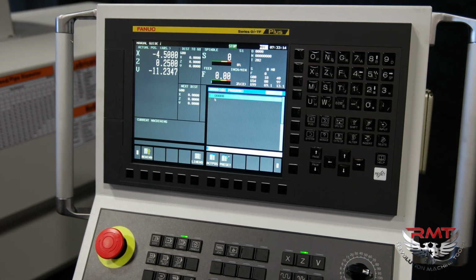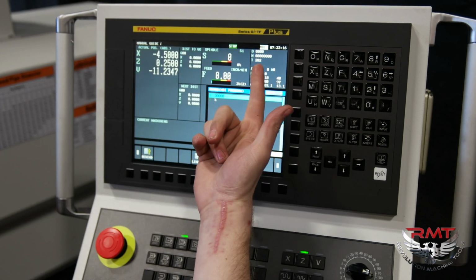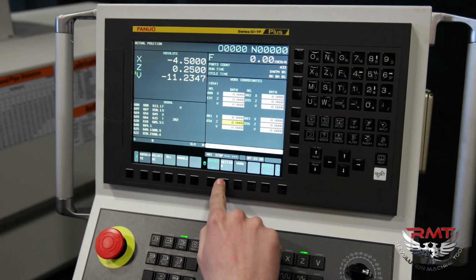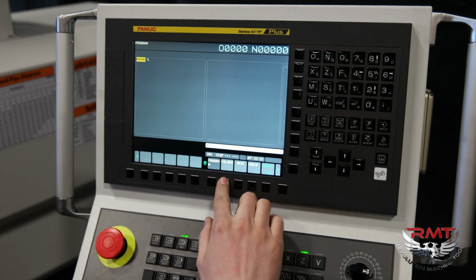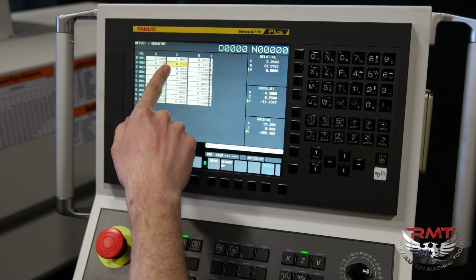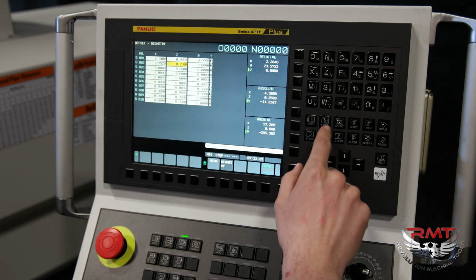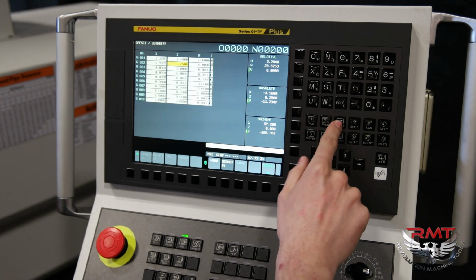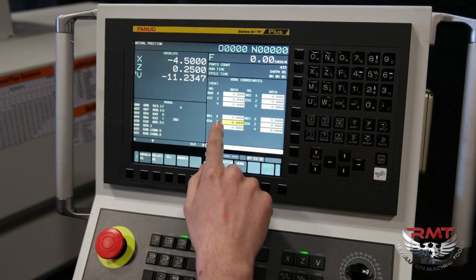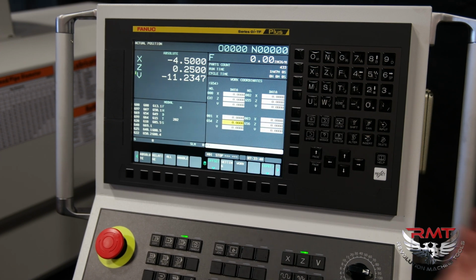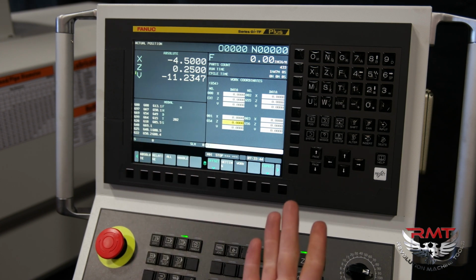any of your tool geometry offsets with a selected tool that has a wear offset, or a Z offset in the geometry, then if I go back to my work offsets, it should be at 0, because when I touched it off with tool 1, we are referenced to Z0, and I had 0 in my tool 1.